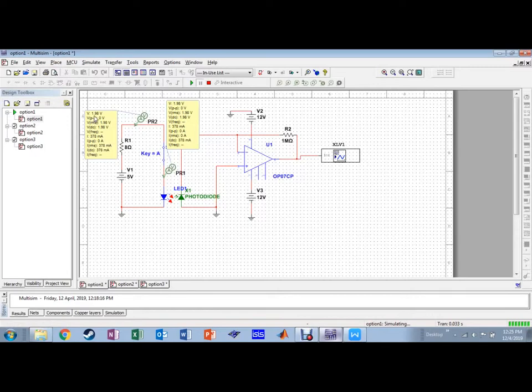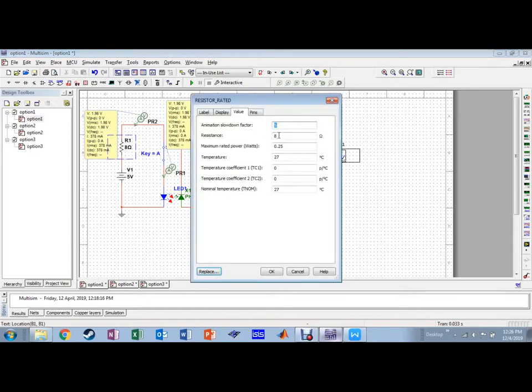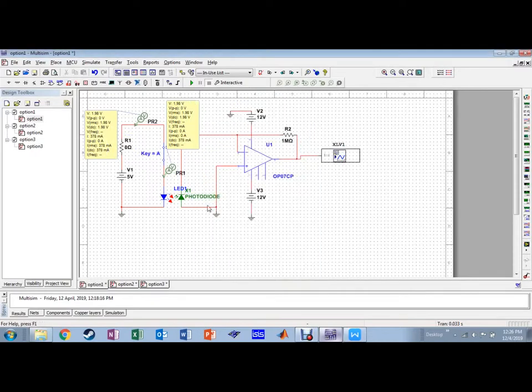The voltage shows 1.9798 volt and 378 milliampere. There is a slight change in the value, but the value stays the same at points E and C. So let's try for 0 ohm. Run it. The voltage shows 5 volt at both points and 1.11 kiloampere. Quite a high current.